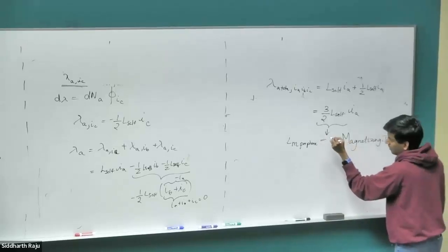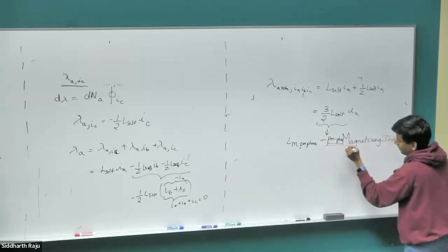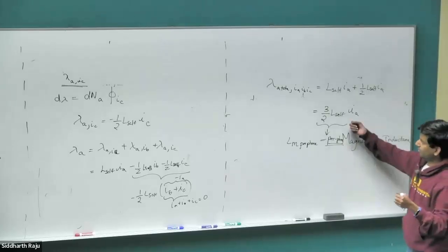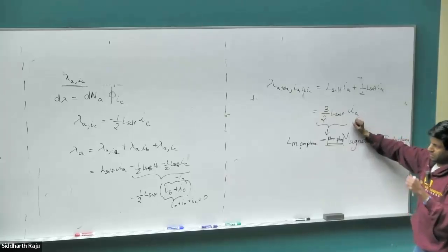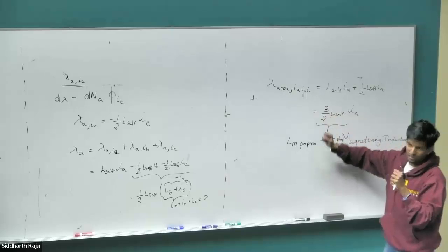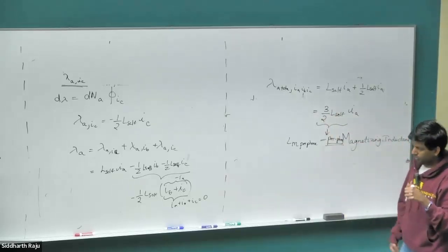So this is the per phase magnetizing inductance. Okay? Because what the per phase equivalent model does is it folds the information of all the other phases into a single phase winding. This captures the information that there is current in the B phase and current in the C phase, which is effectively modifying the inductance of the A phase coil somehow. So that's what this whole thing is.